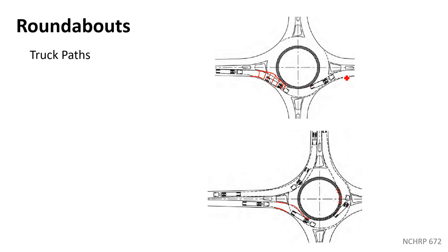Now, if he's going out this side, he doesn't use a lot of that path, just a little bit of it. If you're turning left, you come around 3/4 of the circle, those tires may be out there quite a bit. And so we try to control fastest path with the passenger car by building these islands in certain locations so that they have to arc their path enough to be slower.